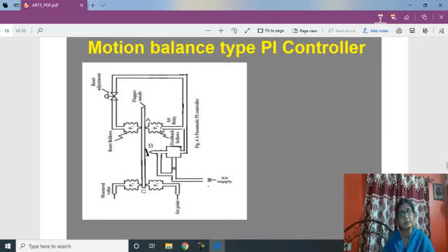This is called the proportional bellows, our feedback bellows, and this is called the integral bellows or reset bellows. The point adjacent to this bellows element is called A. The midpoint, which behaves as a flapper, is B, and the point between the measured signal bellows and the set value signal bellows is called C.